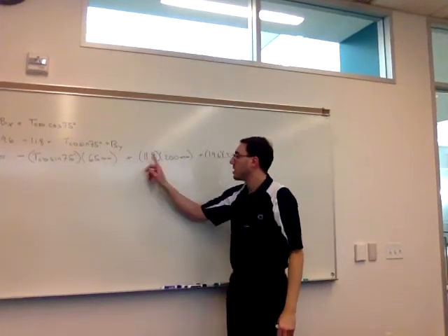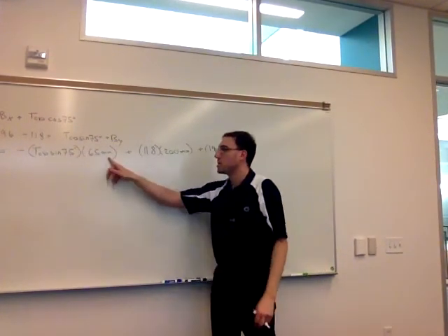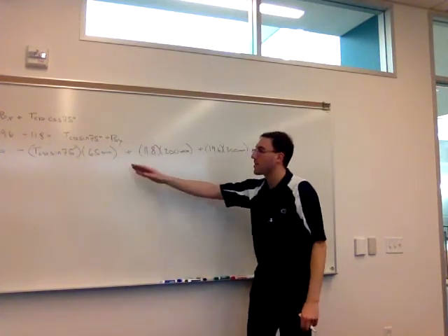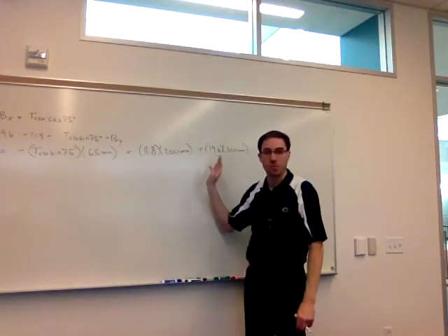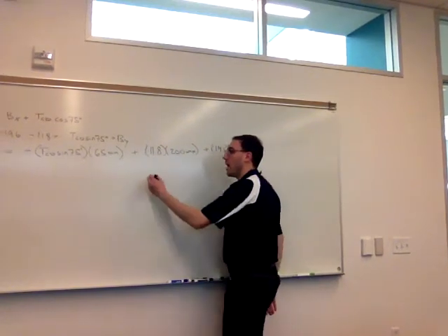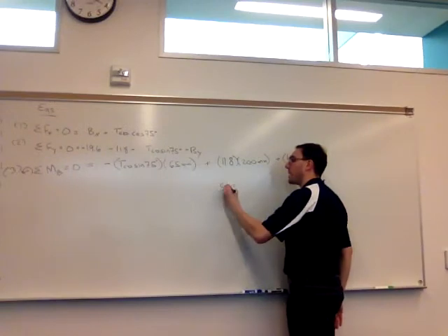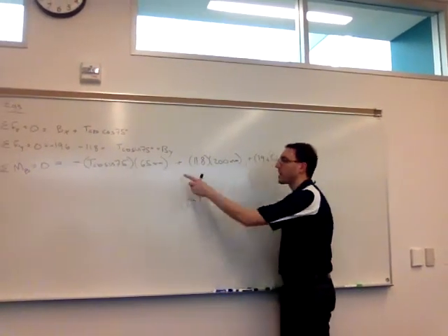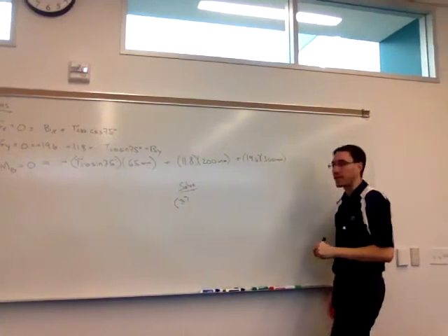As a check, these are all in millimeters, so everything at least lengthwise is compatible here. So as long as everything's in millimeters or everything's in meters, we're okay to use this. So because we've selected point B to take the moment about, equation number 3 is convenient because it has only that one unknown, TCD.